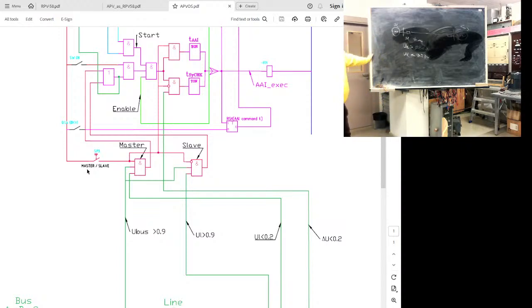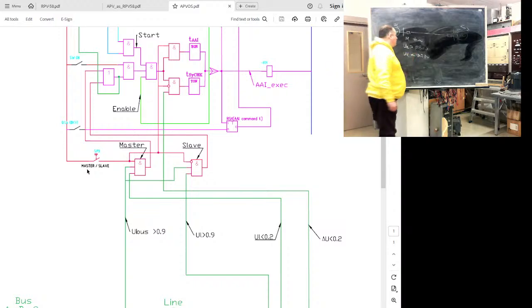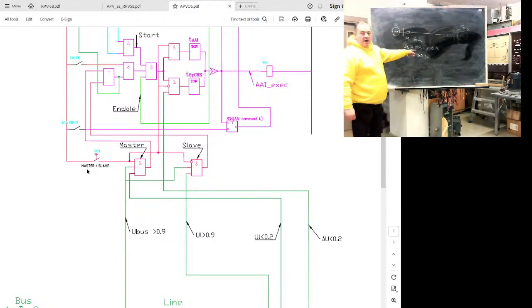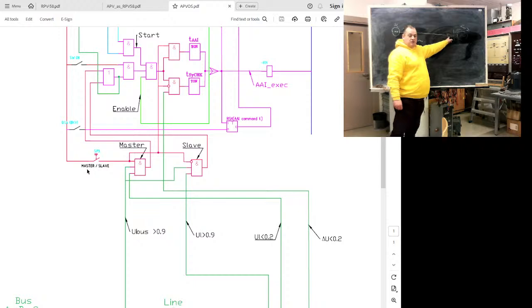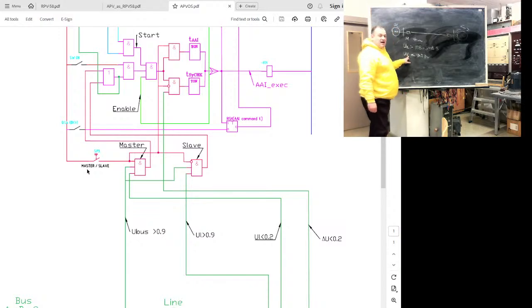Why is it done? First, we have voltage here. We can do reclosing. If there is no voltage, we will do nothing. And second, we check that the line is not energized. 0.2, 0.1, something like this, to prevent false operation from noise. And 0.8, 0.9, something like this. Why is this check there? If the master sees that the line is energized, that means this switch has failed, and we will not perform auto reclosing. If these conditions are met, the master performs auto reclosing.